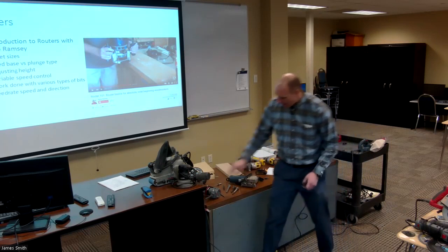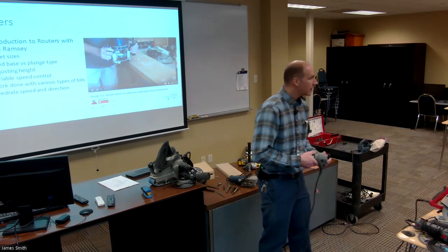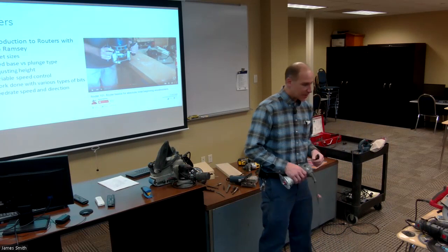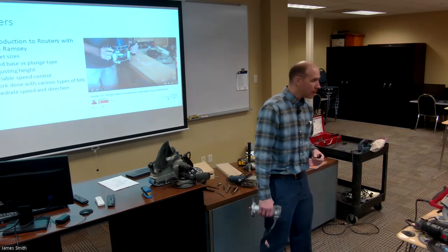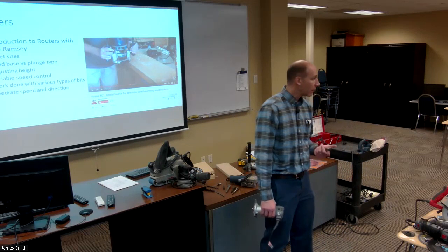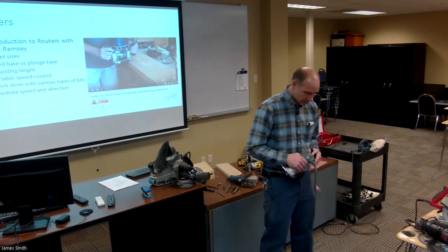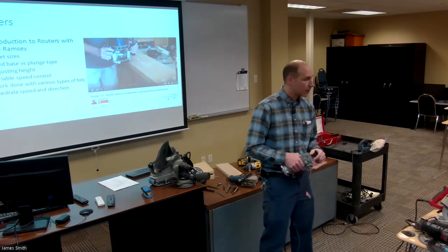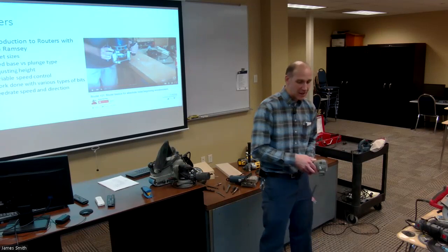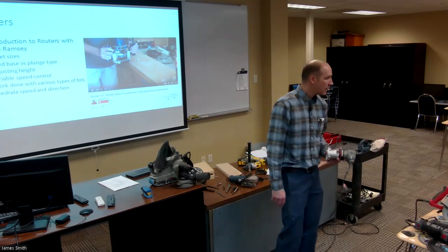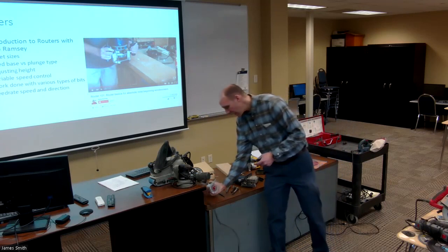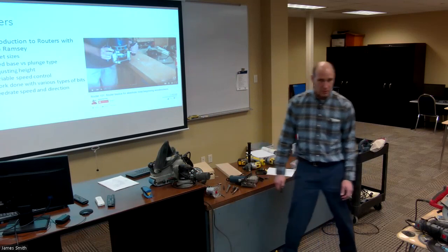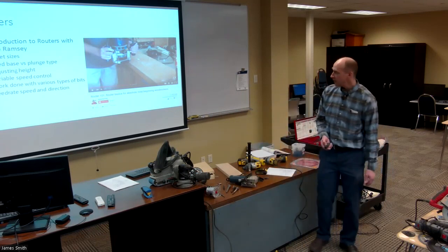Some of these routers will have variable speed, so you can adjust that. But with woodworking, one thing I found is you just run it fast. You use carbide tooling and you don't have to worry about overheating the cutter, okay? In fact, I always run these things full out, and usually when these routers go bad, it's the variable speed control that goes bad first. And so if I can, I always try to buy the fixed speed if I'm using them for wood, because you really have no need to change your feed rate that way. But it seems like anymore, all you can buy is variable speed. So hopefully they get that figured out.